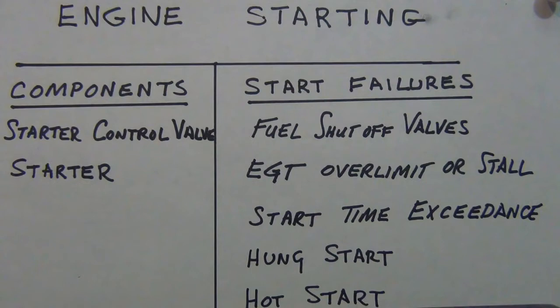Let's say you have the high pressure fuel valve that doesn't open when it should, then you're going to have those aural warnings. Remember I said it's the same type of warning. You're going to have a single chime along with the master caution light that will come on, and the engine fault lights are going to come on as well. That's all going to show up on the ECAM as the ECAM messages. Now the FADEC, if you're on automatic mode, is going to pick that up, and then it's going to abort the sequence. Basically, it's going to start shutting that down.